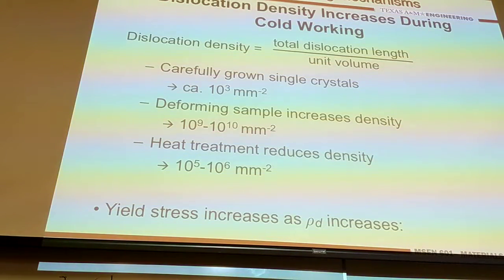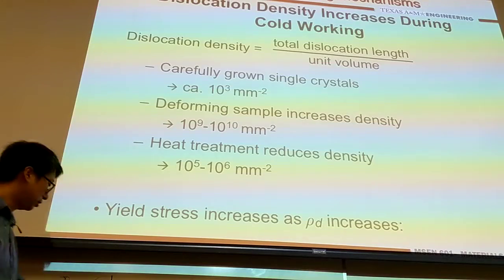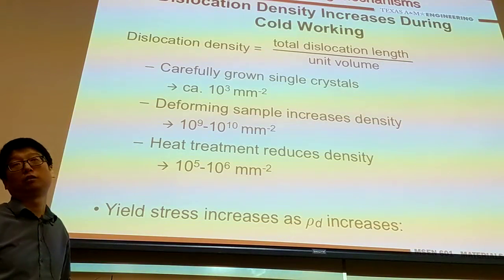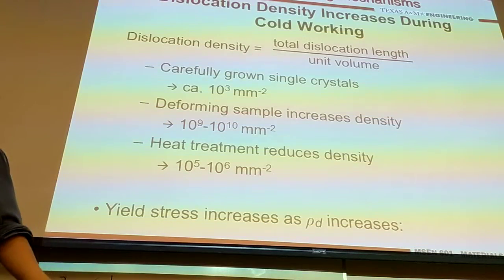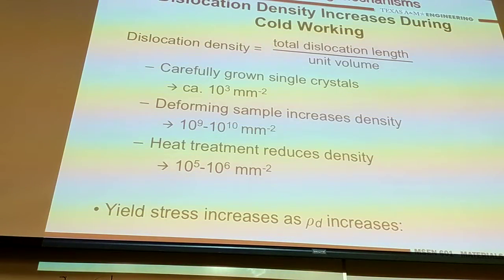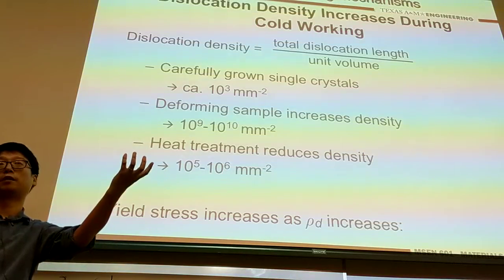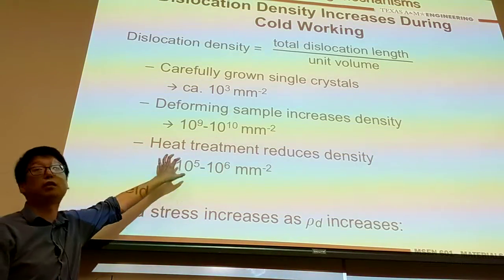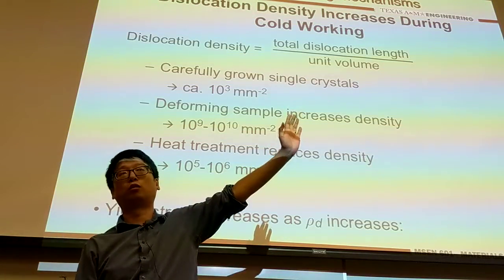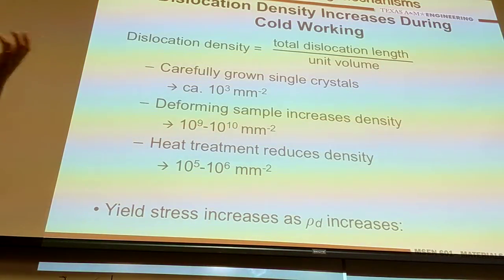The reason is that in industry, if you want to make materials with specific properties, you are not only emphasizing the yield strength, you also want to achieve, for example, the corresponding ductility. You don't just do one step; you want to do multiple steps to achieve a combination of nice properties given certain constraints. So what you need to do is cold work and deform, for example, the sample shape, then do heat treatment to go back to the relatively original property, and then do another cold work so that I can reach the range of material properties that I want. I will show one example in this class.